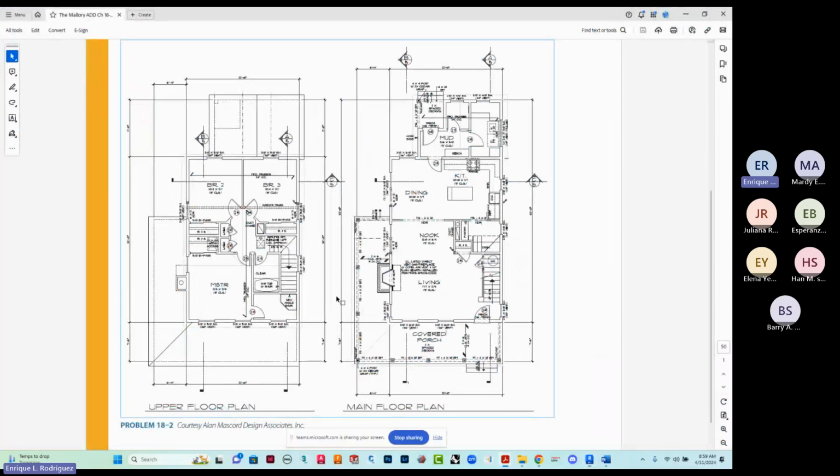Now, in real construction, you would have what's called a composite wall. It's made up of different components, such as the stud, then the sheathing, the drywall on the inside, maybe siding, maybe an airspace, et cetera, et cetera. We're going to go generic on this. And what I mean by generic is one of the wall selections that you have is generic 8, generic 6, generic 4. For the exterior walls, we're going to use generic 6. With one exception, for the interior walls, we're going to use generic 4.